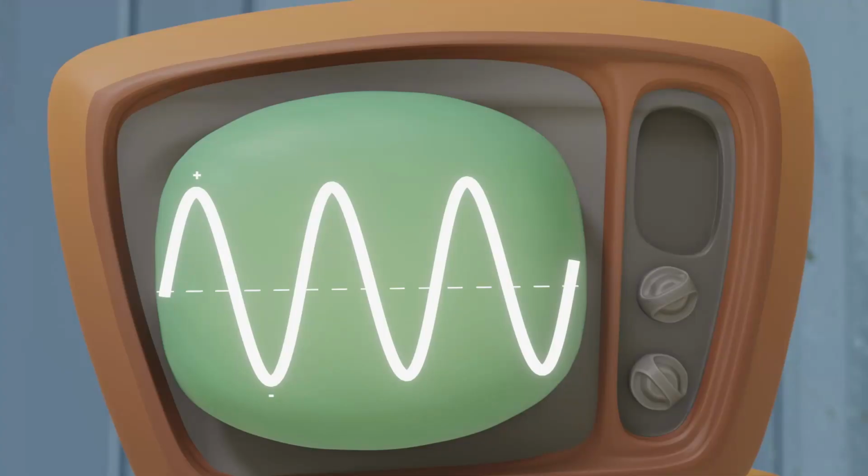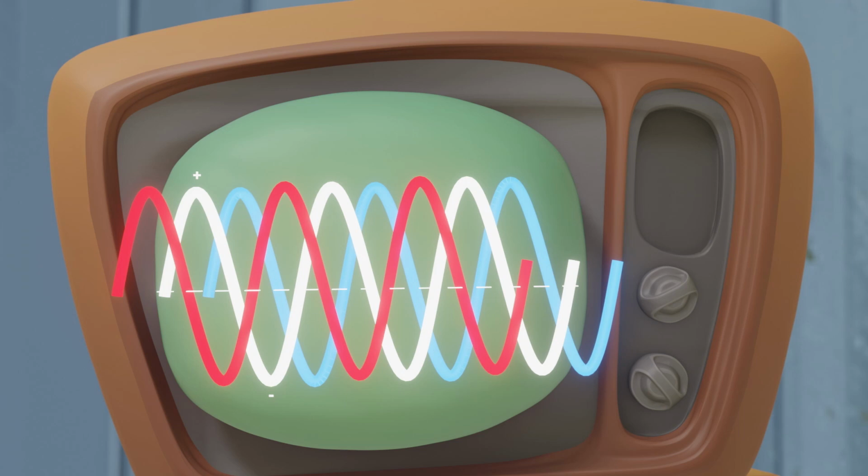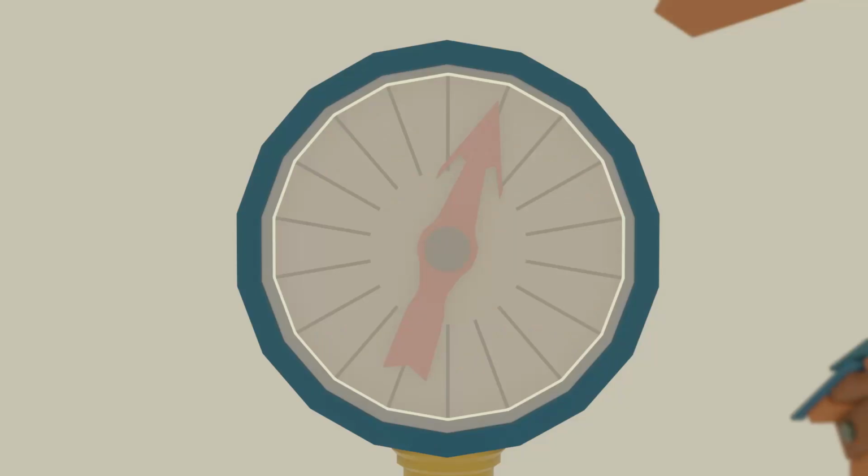Power distribution with AC current gets more complicated again as multiple phases are introduced and run on different lines. The advantage of this multi-phase power, often 3 phases, is that by connecting multiple phases of power to a load, the effective voltage is no longer from peak to neutral, but instead from phase to phase. With 3-phase power in Australia providing 400 volts, however in practice it is much closer to 415.